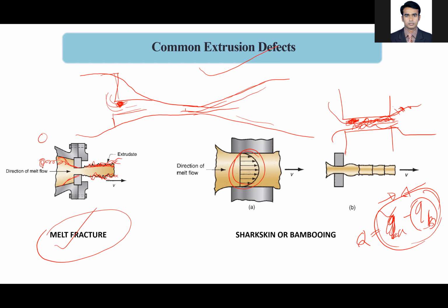Okay, the temperature difference. In the metering section, what happens is that the material is uniformly mixed, and due to the mixing, the temperature becomes uniform throughout the material. There might be a little difference from the outer surface to the inner, but due to the continuous rotation, the temperature is uniform throughout the material.